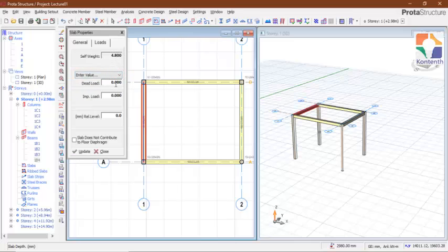Other loads you might want to enter would be if there are some predefined values there, like flat roof. What is the slab going to be used for? A flat roof, a room, a terrace, or a lowered slab. So let's say flat roof. If it's a flat roof, it has a dead load of 1 kilonewton per meter square.